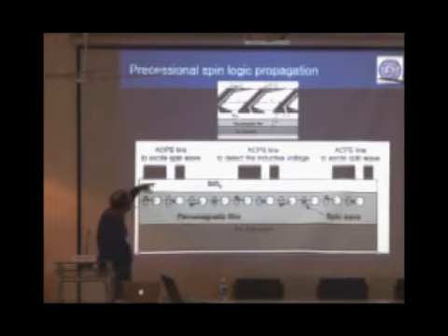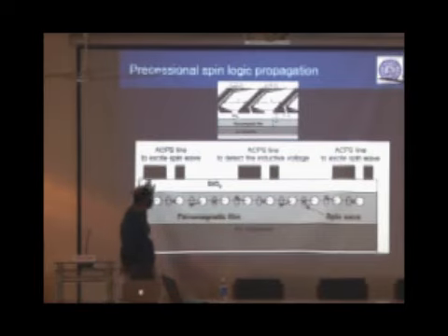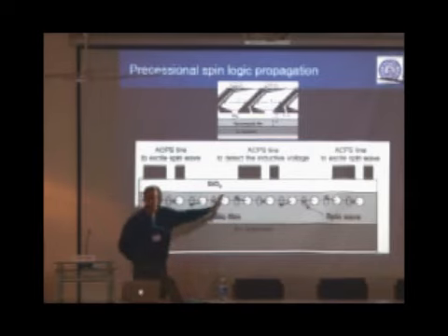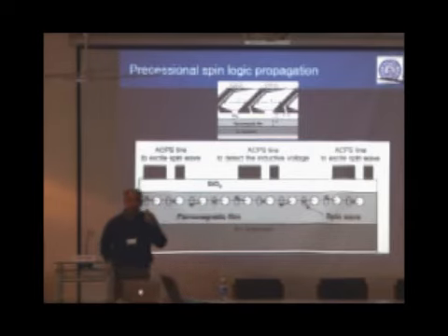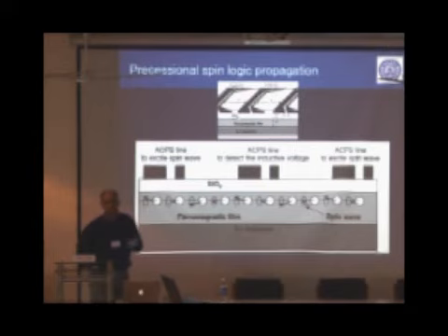So we usually pattern what are called asymmetric coplanar waveguides atop the ferromagnetic film. There are some other geometries where we apply the same thing below the ferromagnetic film as well. And what you are doing is, as the spin wave is precessing from this point to another point, you are launching what we'll call a logic signal from one end of the chip to the other.